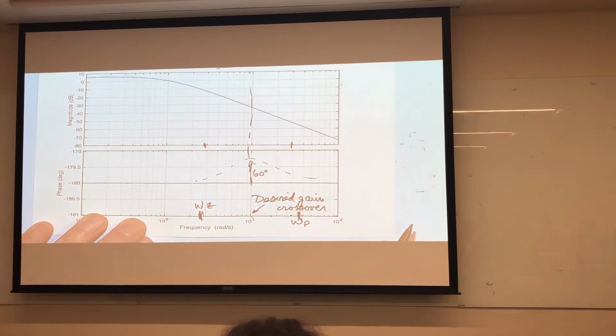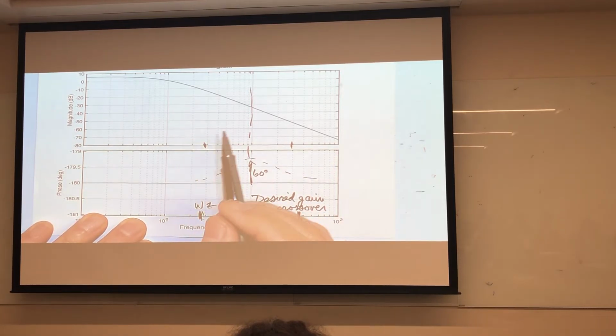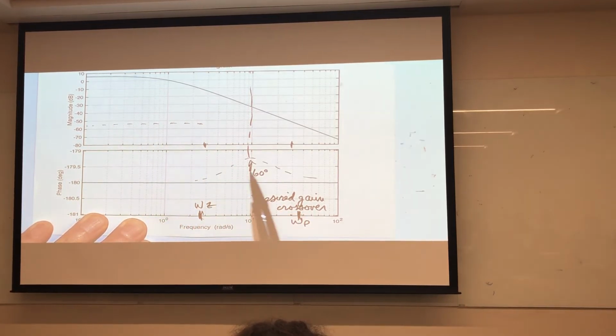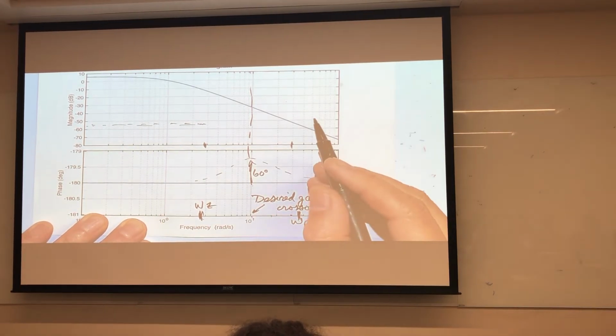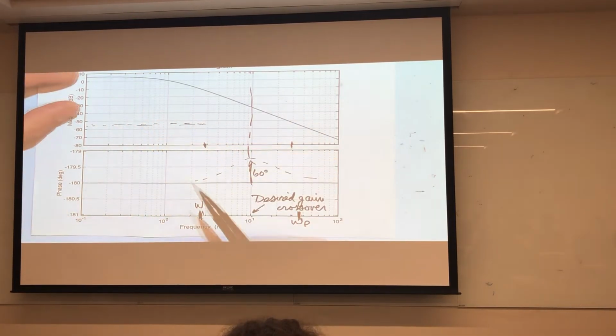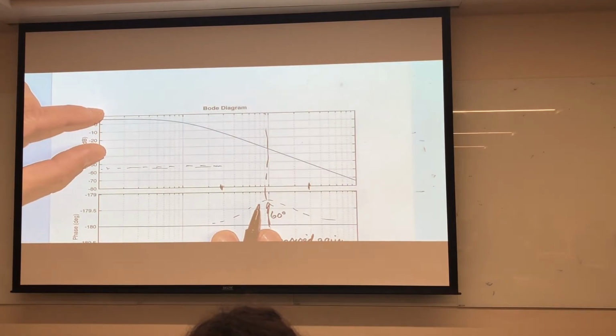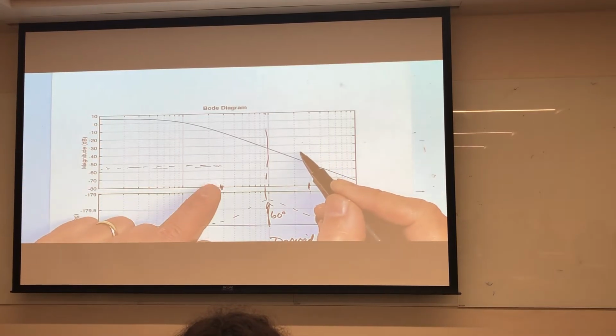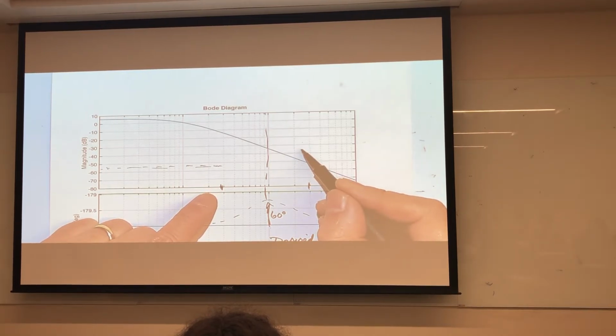So what's going to happen now is we're going to put in a compensator. I'm just going to sketch in the compensator somewhere, any old place, right about here. Here's the compensator gain. And this is going to start rising at a gain of 20 dB per decade. So 20 dB is about this much. So in 1 decade, it would go up about 20 dB.